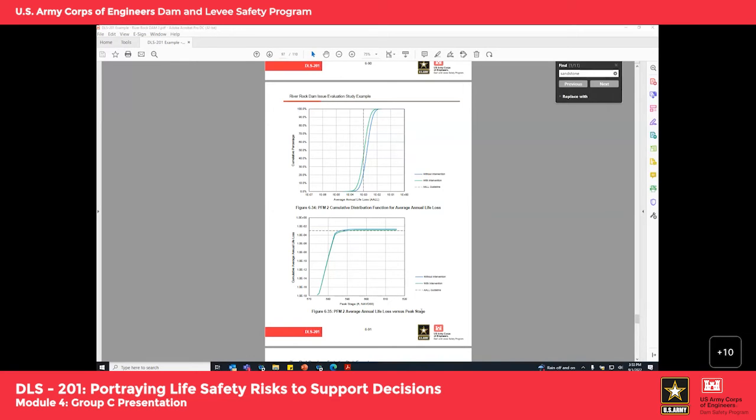That's an indication that you're not really getting a lot of risk contribution from pools greater than that elevation. So that's the question I'm asking: which intervals of pool are really driving the risk once you put together your AEP, your performance, and your consequences?